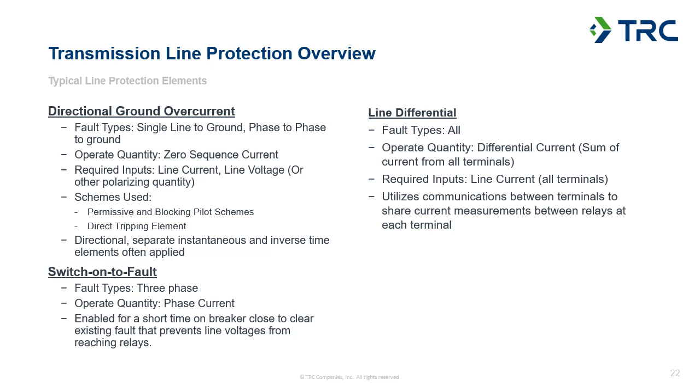We also have switch onto fault protection. That's another type of protection that's there to cover a very specific use case: a three-phase fault when you close in a breaker to first energize a line. It looks at the phase current, and that can be set pretty sensitive because the element itself is only enabled for a very short period of time upon breaker closing.